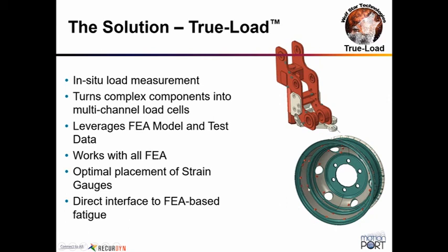With that information from the unit load cases applied to the different locations of attachment and so forth, and then with the actual time history from the actual strain gauges applied, it uses all these unit load cases to come up with the true load condition that caused those strains throughout that component.